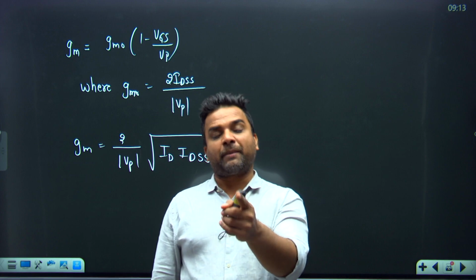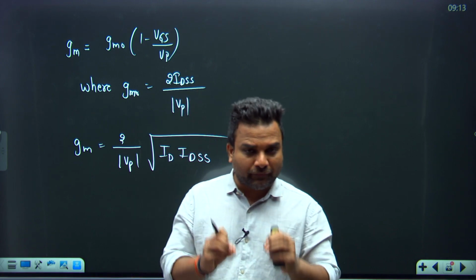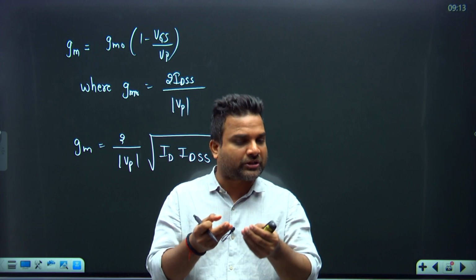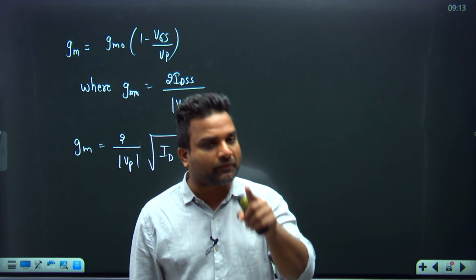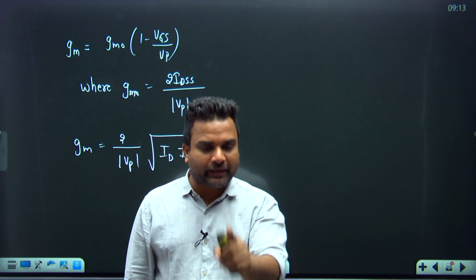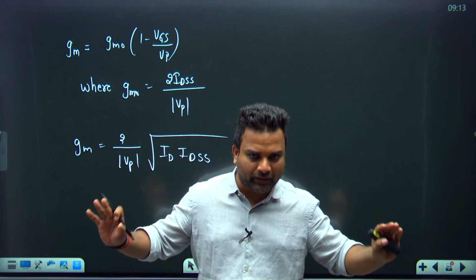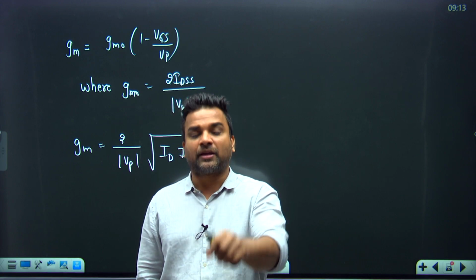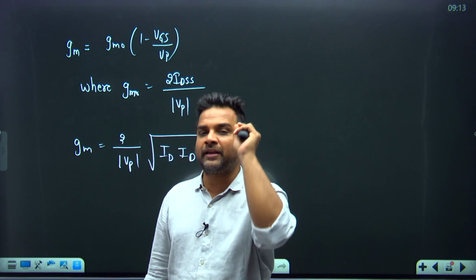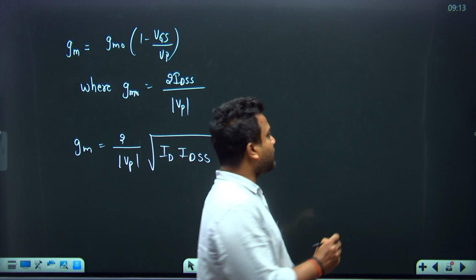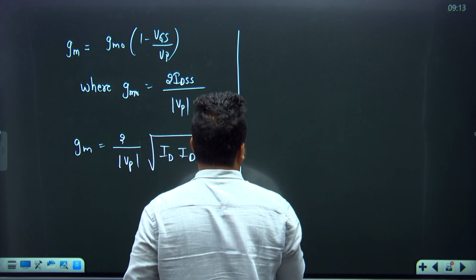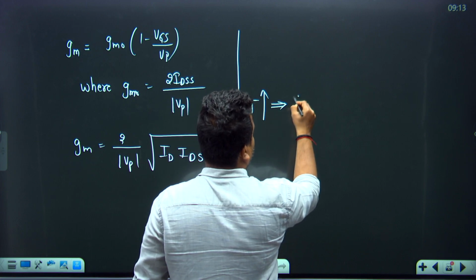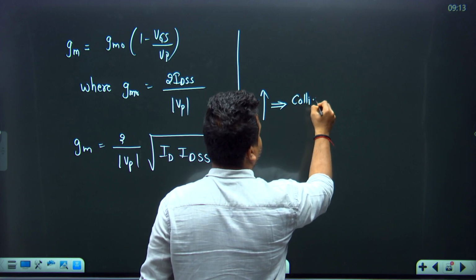Moreover, whenever temperature increases, in the FET channel, among the charge carriers there will be collisions. Because of the collisions, the mobility decreases. If mobility decreases, definitely current reduces. If current reduces, drain resistance increases. So guys, we can say clearly, as temperature increases, collisions occur.